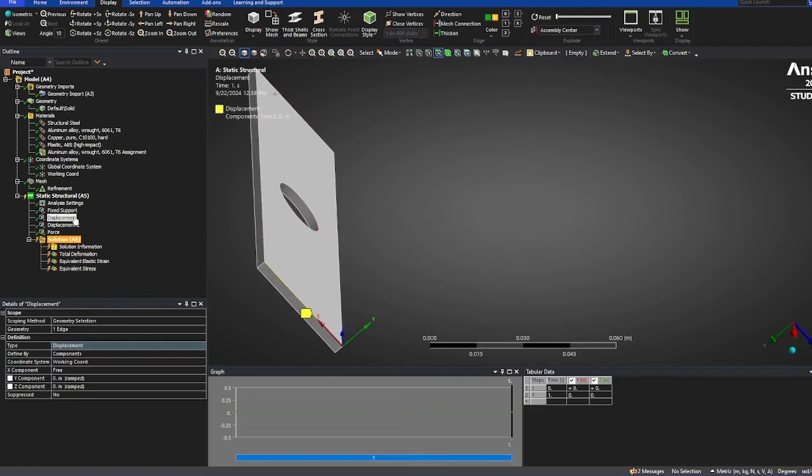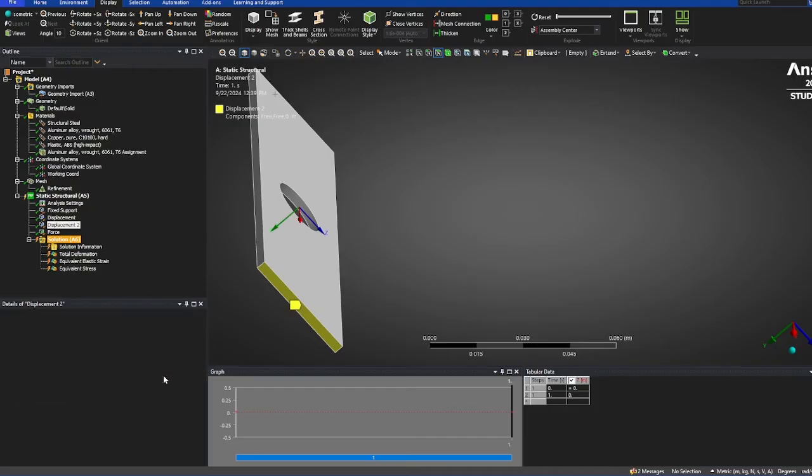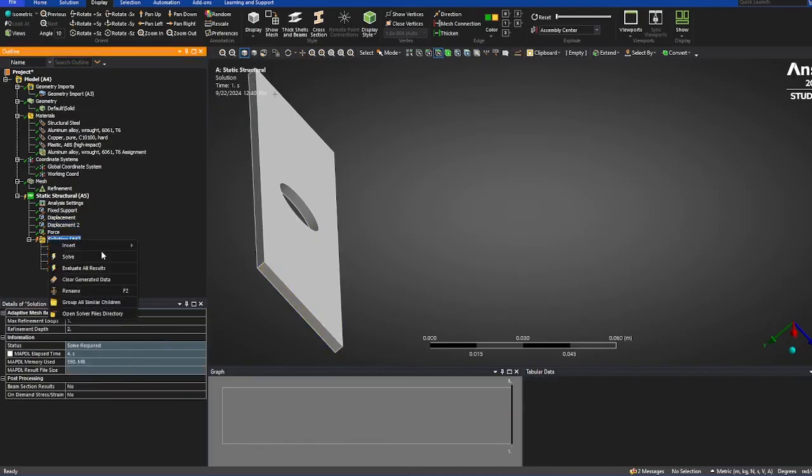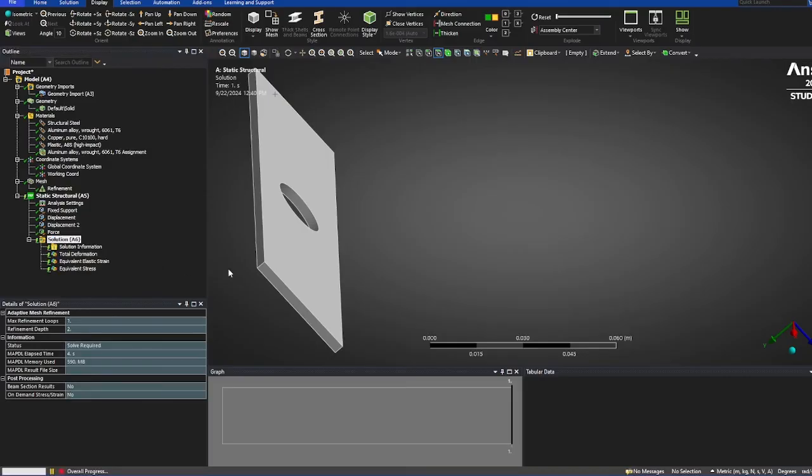In this case, and I'm wondering if any of you caught this when I was setting it up, I forgot to include the proper origin for one of my displacements. So if you click on that, you can actually see that it's originally at the center, and I can modify this and say, hey, you are supposed to actually be this origin. You may have made a different error. It may just be that you chose the wrong displacement of 0 for different parts. It's important that you check that, because that's probably the most common error that we end up seeing from students when they come to us.